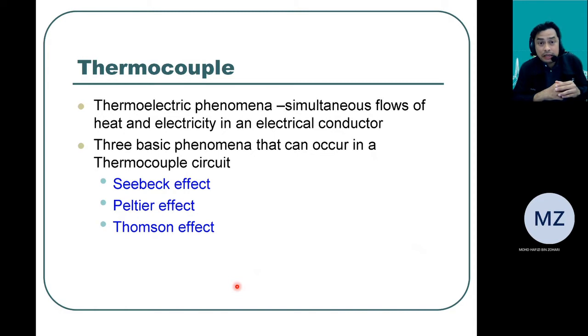Why is the EMF produced if we combine these two materials and form that particular design? Actually because of three main effects, which are the Seebeck effect, Peltier effect, and Thomson effect. But the most is the Seebeck effect. Seebeck effect contributes the most of the EMF generation in the thermocouple.